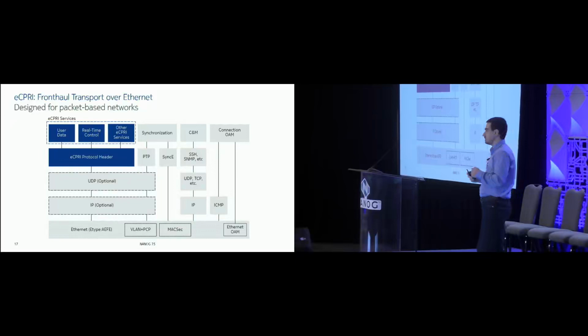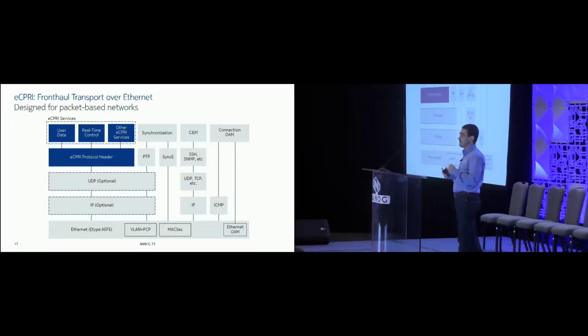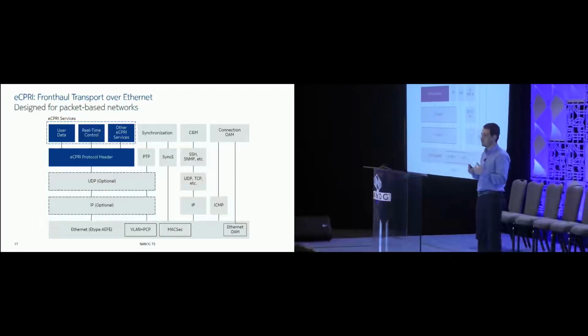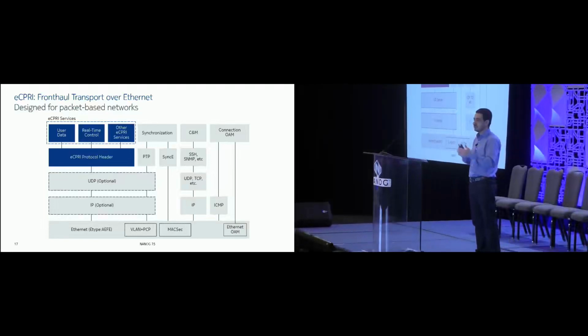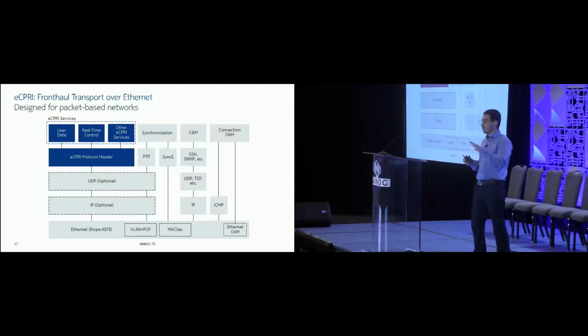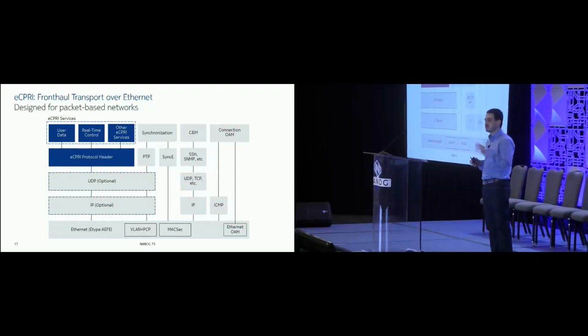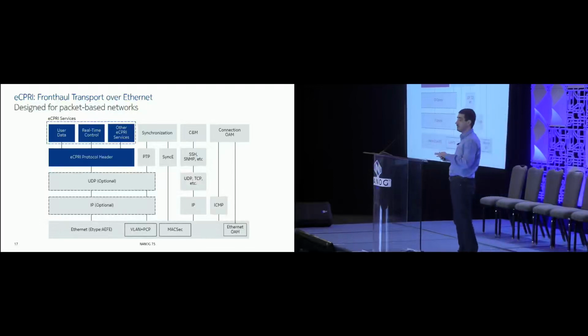In 4G, time and phase can also be mandatory if you use some specific techniques like TDOA for increasing the precision of localization of users in location-based services. In the US, that is very much used. In Canada, for example, and in other countries, it's not. You might get away with just frequency synchronization for 4G, but not for 5G. 5G will require time and phase synchronization.